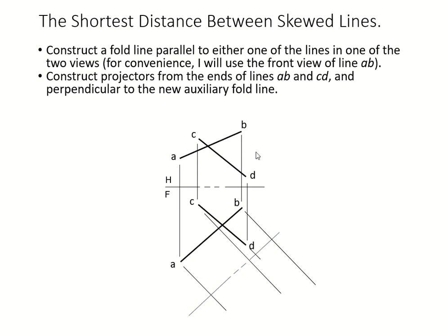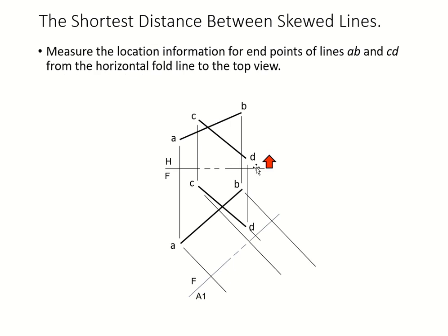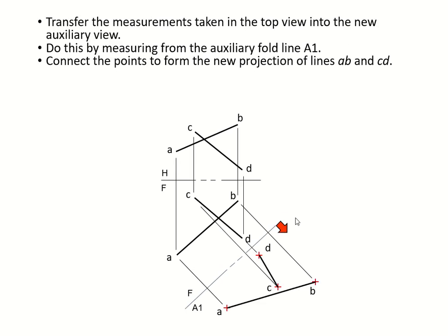Because it's easier to draw in this way, because in this example we have space on this side, so depends on how you want to do, either this way or this way is better. So AB parallel to the second fold line. Your projector lines coming out from your front view do the same thing. Direction of your distance, right? Measure. Yeah, we are going to project it to this direction, the same dimension as that, and we get all of our points.